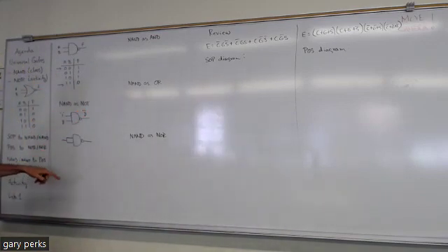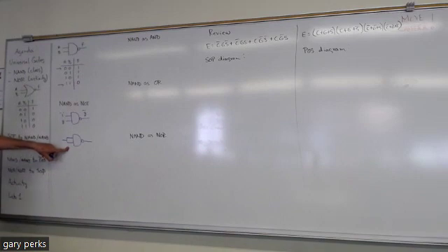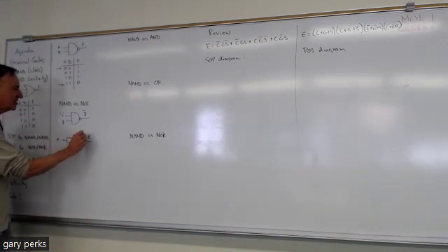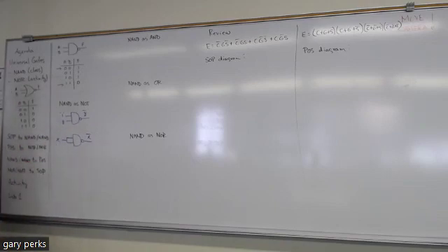So if you connect 2 things together, it forces them to be the same voltage. Remember, the 0s just represent 0 voltage and the 1s just represent some plus amount of voltage. So these are 2 different ways that you can make a NAND gate into a NOT gate. Whatever you call this input, you're going to get the opposite out. Any questions on either one of these, how these work?